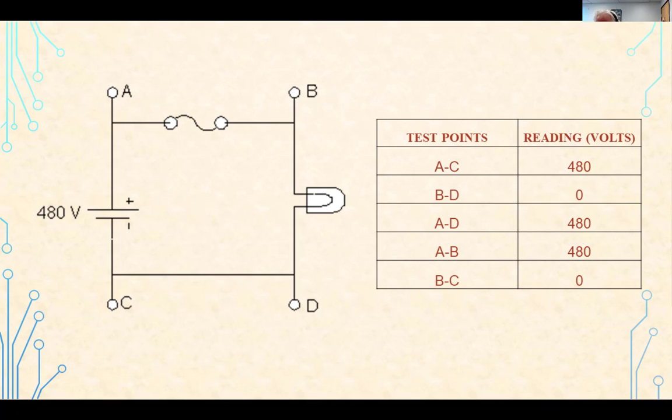Those are characteristics of faults. Just about the only kind of fault you're ever going to have in an electrical circuit. It's either going to be short circuit or open circuit. You can't see them a lot of times. You have to be able to find them using measurements. And so that's the purpose of this. I used a meter to obtain measurements, and now I've got to analyze my results to tell me what the situation is. Anybody want to give a shot at this? Just fuse good or bad?